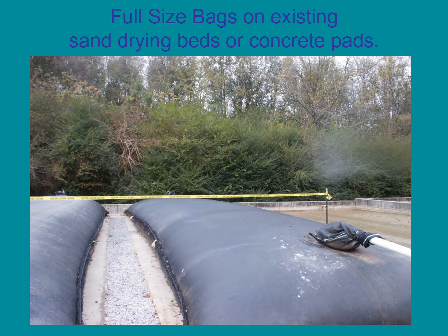The geotextile bed bag process uses bags sewn into long tube-type shapes. The bags can be laid out on existing sand drying beds, or they can be placed on special concrete dewatering pads.